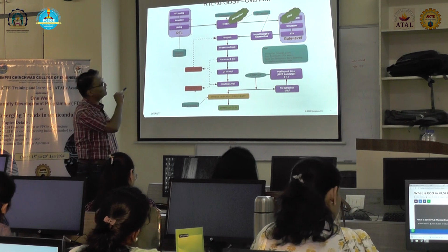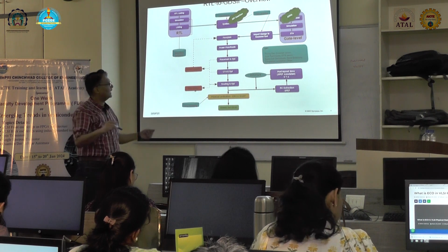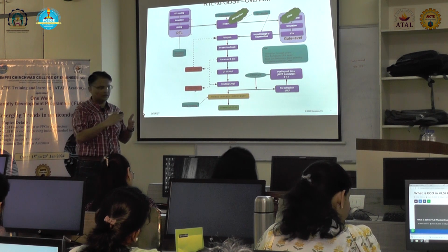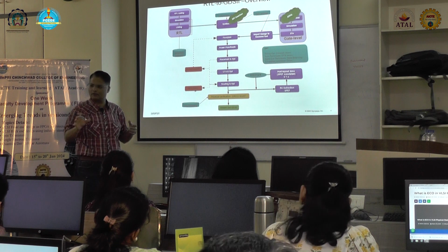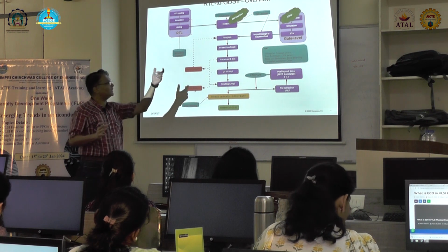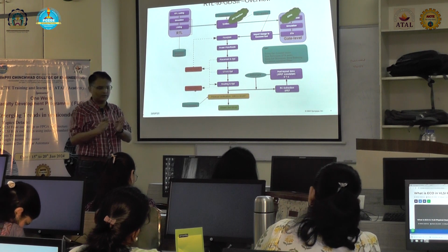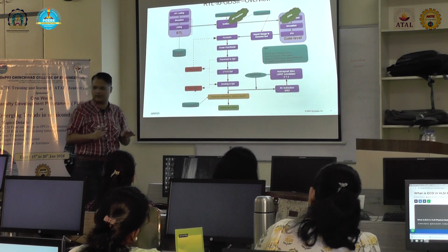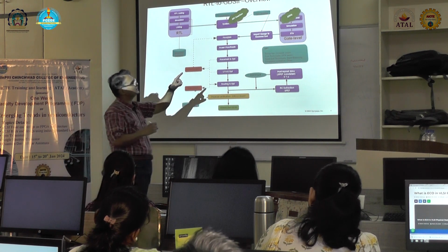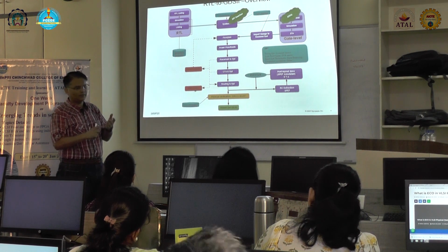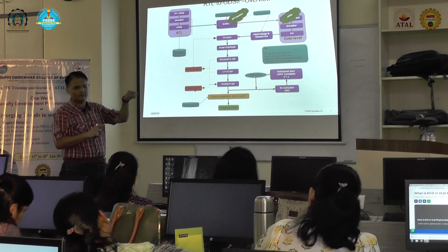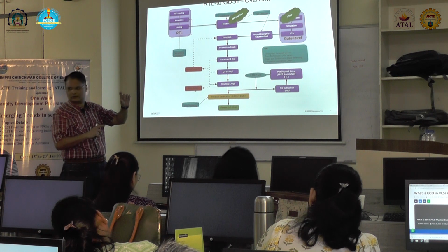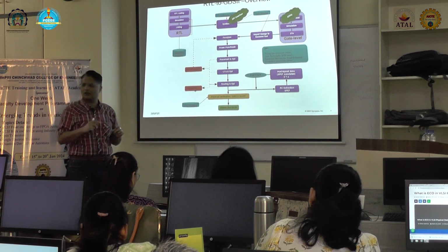Okay. So we will create some scan chains, and there is a shift pattern. During scan, you shift in a pattern, and you shift out that pattern as well, and you analyze that output pattern. The ATPG vector will tell you whether the pattern matched what the design house has given. So, when giving the chip for fabrication, we have to give the ATPG vector to them. The ATPG vector consists of input stimulus plus expected output stimulus. Okay, they will run this ATPG.